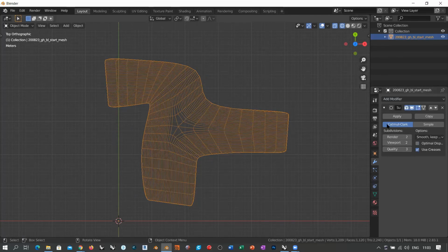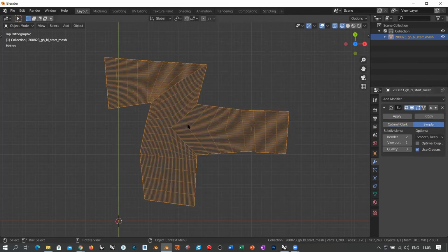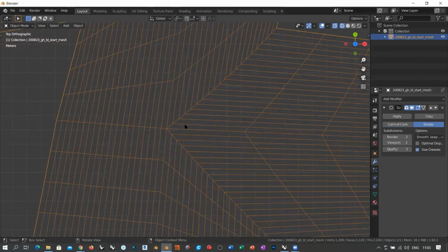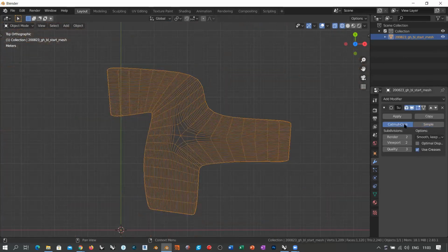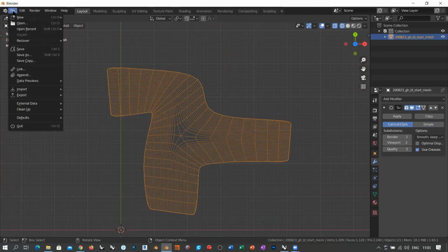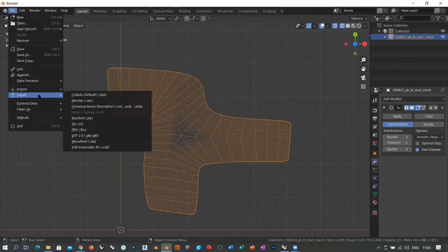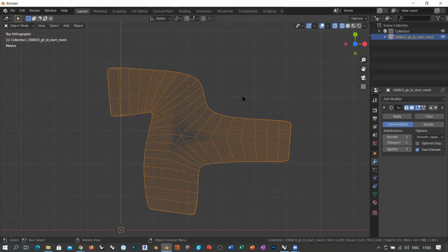If you want it with some smoothing, then you use Catmull-Clark. If you want it simple, then just pick the simple. But the loops are always turning around these corners here and this corner here. Okay, but if you want to work with Catmull-Clark, it's going to be even more interesting. Okay, so once you have this, you can re-export this object as an OBJ, re-import it in Rhino, and we'll see how Kangaroo works with this kind of thing. Okay,